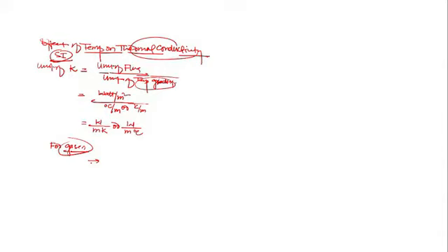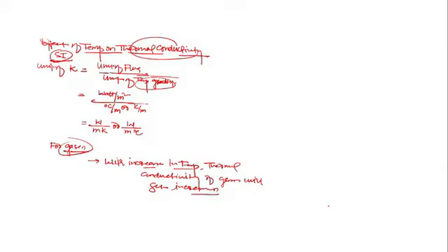Yes or no? So if we increase the temperature, let's say any system is at a temperature of 25 degrees Celsius, and in the same system now it is at 35 degrees Celsius, and now 50 degrees Celsius. As temperature increases, compared to 35 and 25, the kinetic energy is more, then there is more random motion, then the net transfer of energy is comparatively more than at 25 and 35. Yes or no? At 50 degrees Celsius. So that's why in gases, with an increase in temperature, the thermal conductivity of the gases will increase. Clear, beta? Reason clear? Any problem? And also with temperature, collisions will also increase.